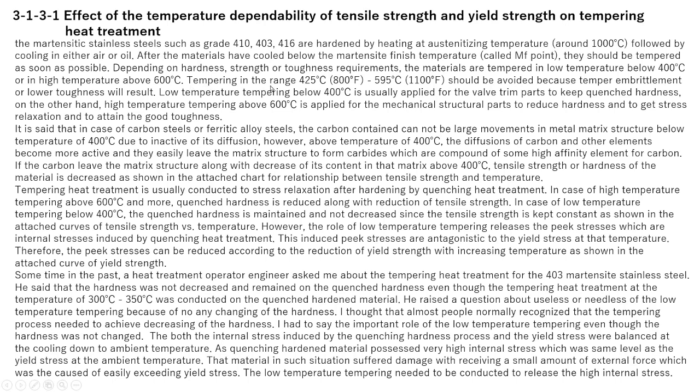Tempering in the range 800 to 1100 Fahrenheit should be avoided because temper embrittlement, or lower toughness, will result.